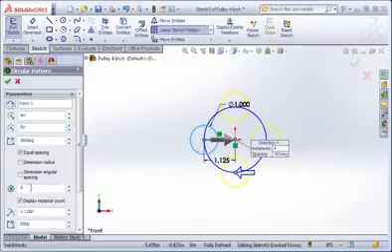and this is the count. Set it to 3. The included angle is set to 360 degrees because the equally spaced option is checked. This option changes the radius of the pattern, and this option changes the location of the center of the array